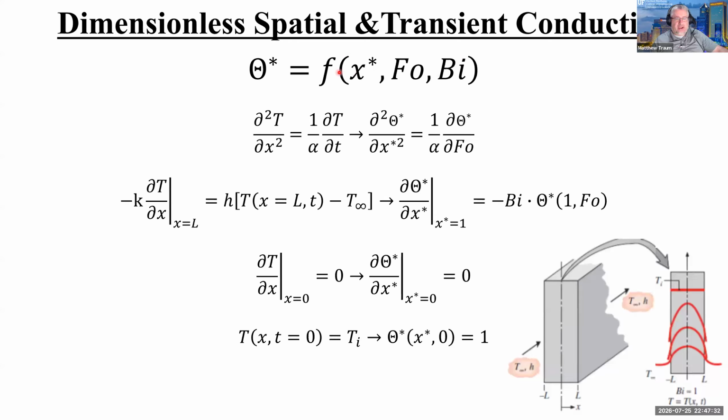Of course, Buckingham pi does not tell us what this functional relationship is, but it does tell us the important variables. And normally, like back in fluids, you'd actually have to run an experiment to figure out what this functional relationship is. In heat transfer, we know what the functional relationship is because we have the diffusion equation, right, which relates all of these variables to each other through an actual mathematical equivalency that arises. If you go all the way back, it's from application of the first law of thermodynamics to an elemental particle that we're then interested in conduction through.